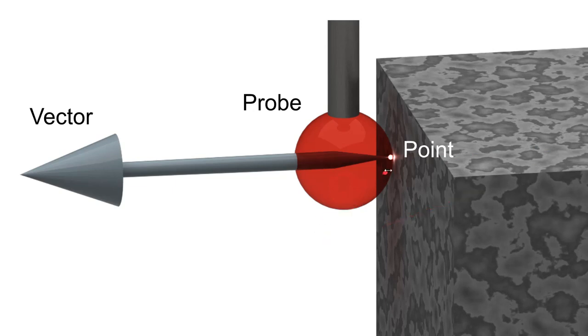So what it has to actually record is not just the fact that it touched this surface, but that it was traveling in this direction toward this face when the contact occurred. And the way it keeps track of that direction is with a vector. Okay, so every CMM hit point, every measurement, has a point and also a vector associated with that point. So this works out really well if you have nice flat surfaces that are perpendicular to the axis that you're traveling in.